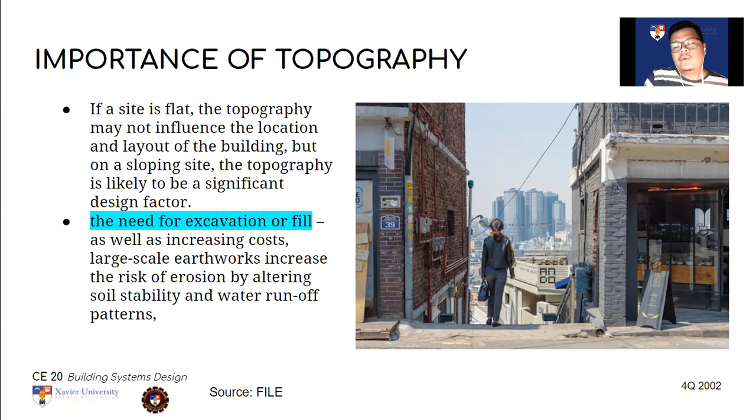Topography is one thing that we need to consider in this aspect. We know that if the site is flat, there's not much consideration for topography. However, if the lot is undulated, that means that topography is not flat. And if the elevation exceeds perhaps 5% to about less than 30%, then there's the need for excavation, land filling, or in some cases, perhaps you need to build your structure to accommodate the available topography of the area. In some countries, laws and zones or even local codes prohibit excavation and land filling, as this may disrupt the already vulnerable structure of the soil.